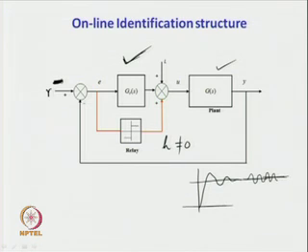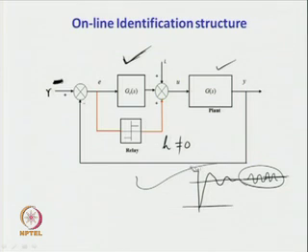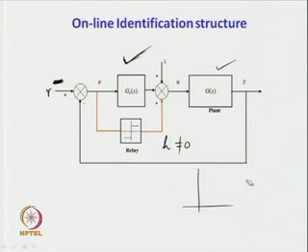This is the beauty. So, during this time we make measurements of the limit cycle output signal and estimate the plant dynamics model parameters. Based on the model parameters, the parameters of the controller are set, and this is how online identification and tuning is done in real time.